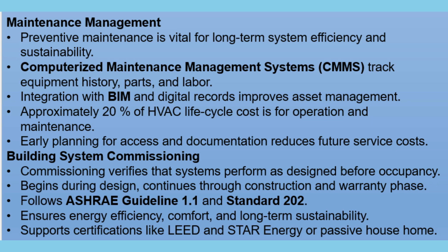Proper maintenance planning during design ensures safety, longevity, and sustainability. Commissioning, meanwhile, ensures the system operates exactly as intended. It begins during design, continues through construction, and extends into occupancy. Following ASHRAE Guideline 1.1 and Standard 202, commissioning verifies performance, comfort, and energy efficiency before handover.